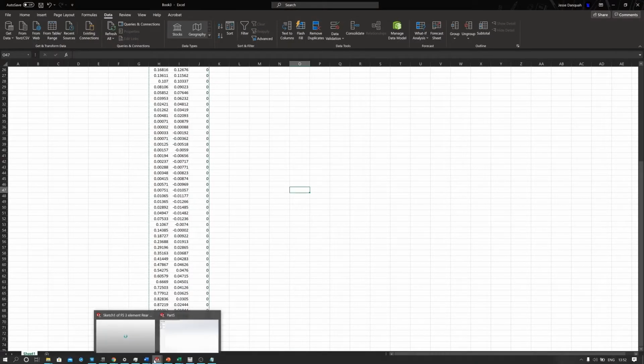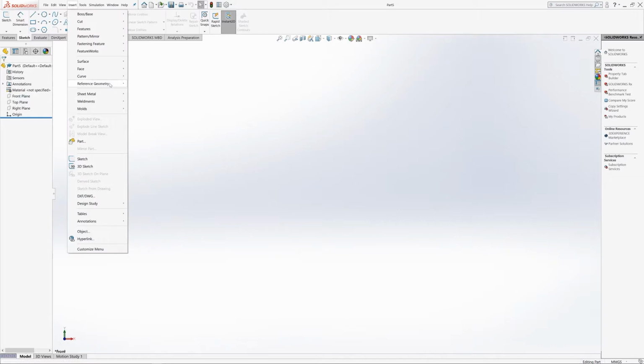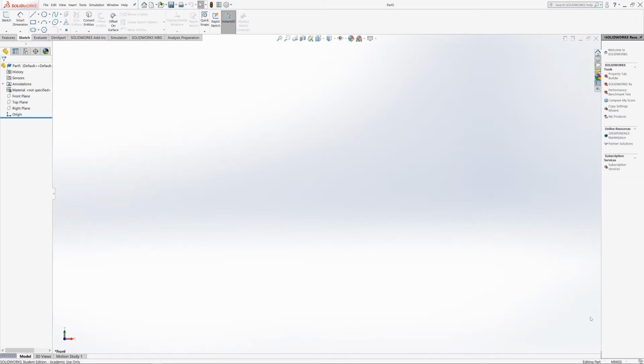So with that, we'd head into SolidWorks and we've got a new fresh part file here. Normal to front plane, and all we're going to do is insert, oh, before I do that actually, make sure you're using the correct unit. So head down here in the bottom right and change to meter, kilogram and second, otherwise you'll have a 1mm airfoil.